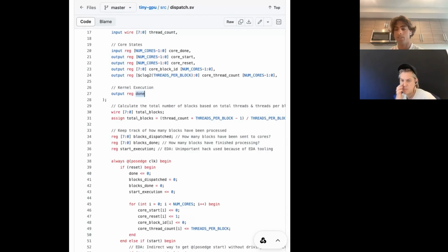Like, you need to synthesize the Verilog down into a logic. There's like a chart of the logic that's specified in there. And then because of the way that people program stuff, that logic is inherently not going to be perfect. It's going to be way more complicated than it needs to be. So you can do some processing to get that logic down into its simplest form that's still equivalent. That process of turning the Verilog into a logic flow is called synthesis. And then once you do that, you can perform a bunch of analysis on whether this design is valid or not. Then you convert that logic that you've created into gates.